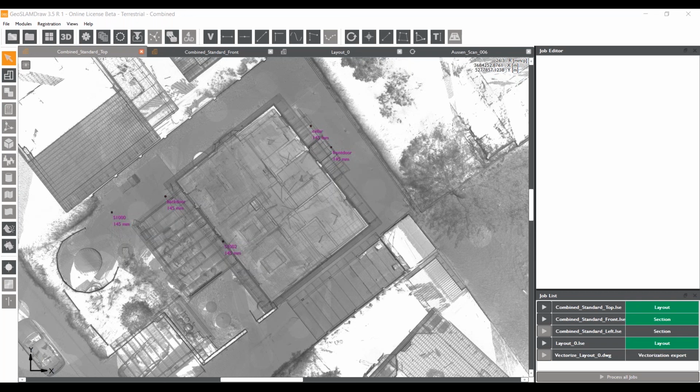Or even if you have some rooms that you can pop into but don't necessarily need in your scan, making loops there will improve the overall accuracy of the scan. If it's just straight, maybe around a box or a couple of chairs, make a smaller loop every 30 meters with Revo and at least every 100 meters with Horizon.